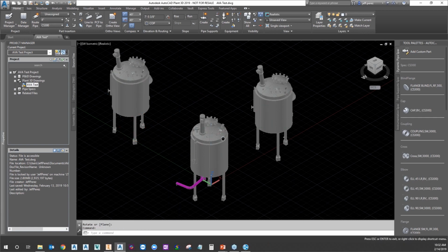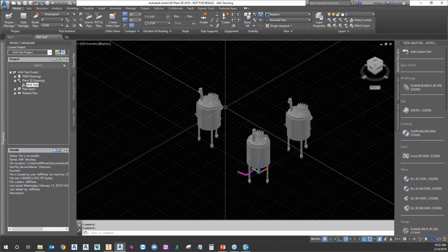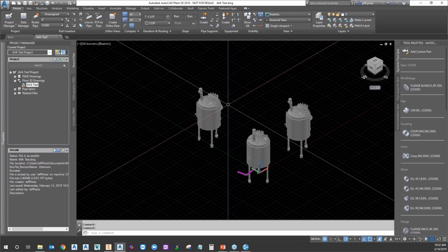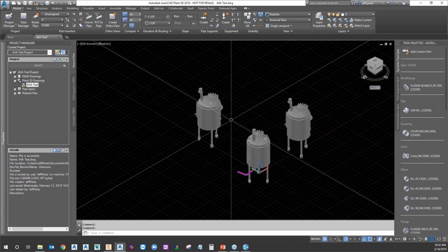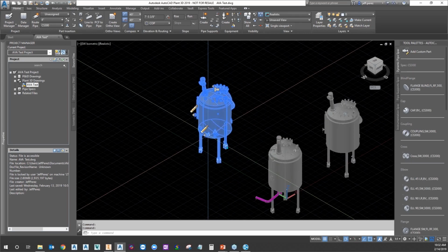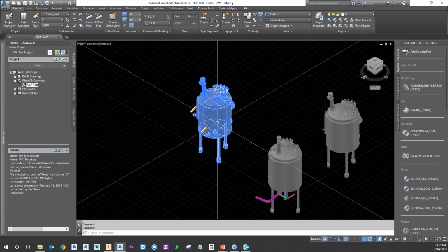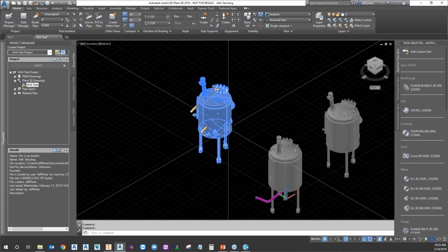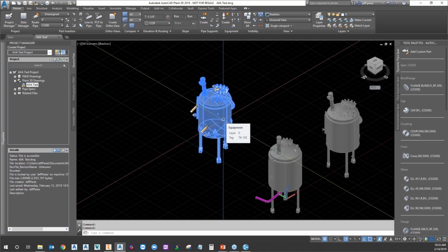So that's how I would actually utilize these parts or these assemblies that I am converting in Inventor, that I actually shrink wrap using a level of detail, substitution level of detail, and then push them into a BIM content, and then brought those over into Plant 3D so I could utilize these and route piping off of them. Now note that because I did author these, the authoring remained within that vessel. So as I stated before, before you create these templates, try to author all your nozzles or any connections that you're planning to route off of.